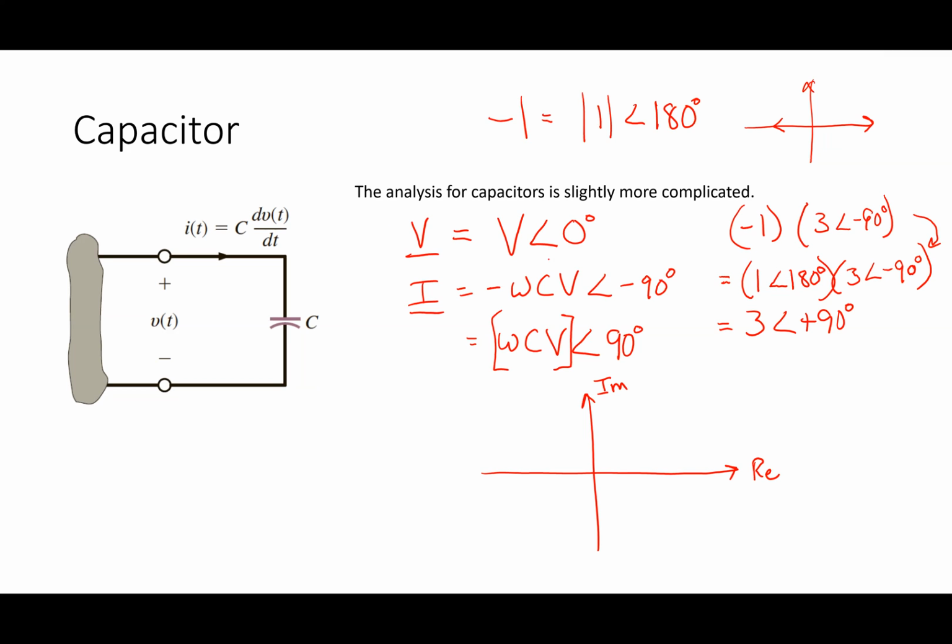The voltage phasor. Where would I draw this guy? Along the real axis. Yeah. So here's V. Where would I be? Imaginary. It would be on the imaginary axis, and would it go up or down? Up. All right, so here's I. What's the angle between them? 90. Okay. So what I see in this particular case is there's always a shift of 90 degrees between current and voltage. And current is always 90 degrees ahead.